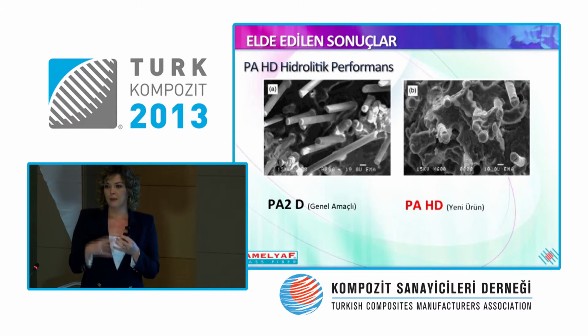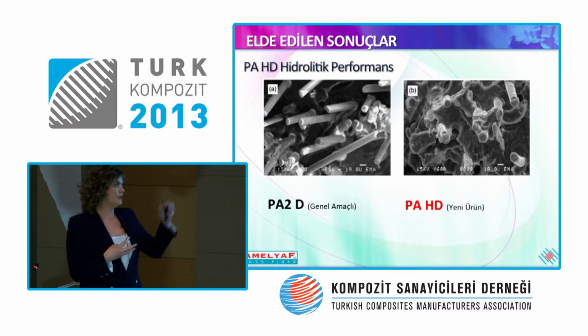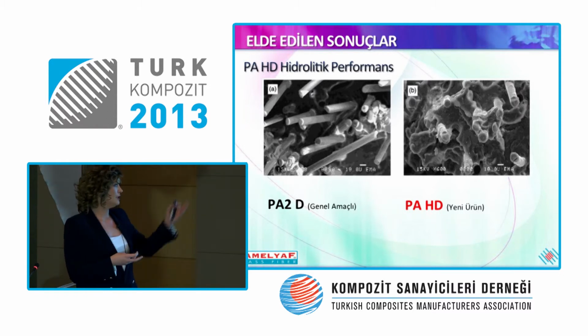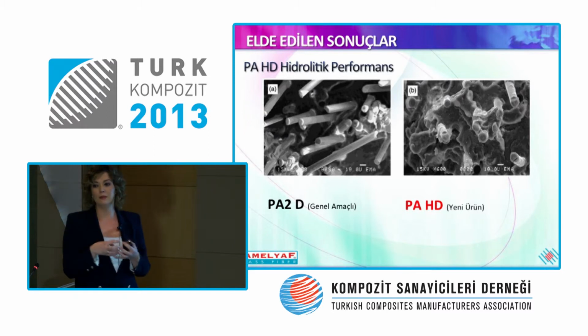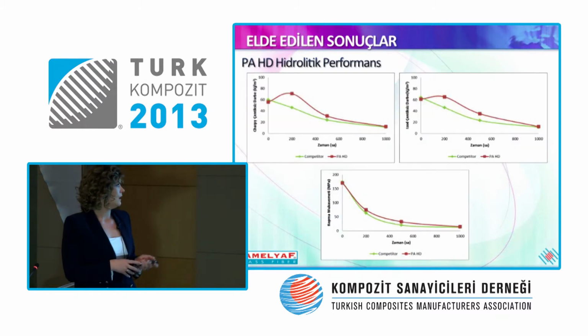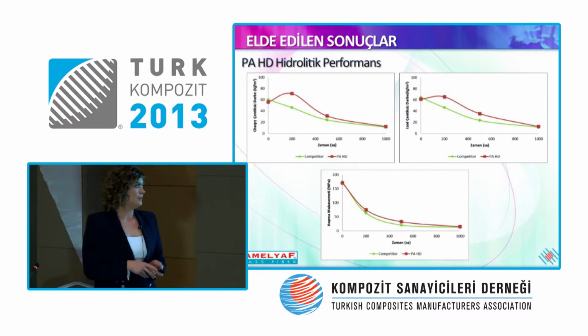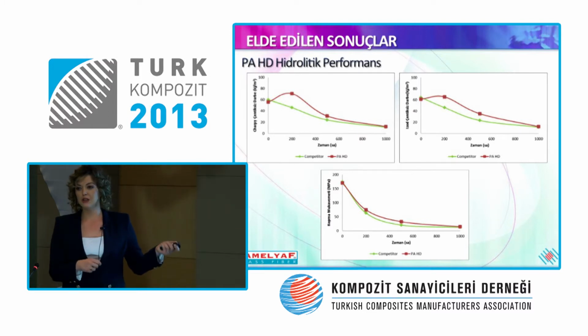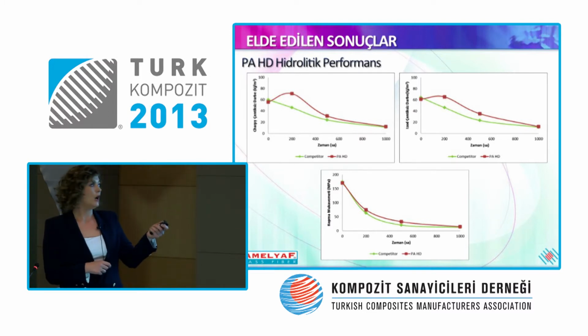The binding agent, the bonding agent, the link between the bonding agent is gone, and it is now a filling agent. But the hydrolytic product, at the end of the 1,000th hour, is still within the matrix and with perfect composition. When we look at the hydrolytic performance, we will see that the Charpy strength is seen here at the end of 1,000 hours.